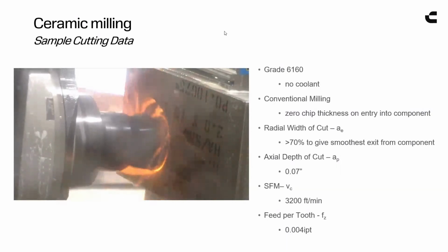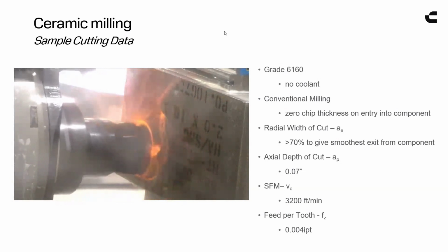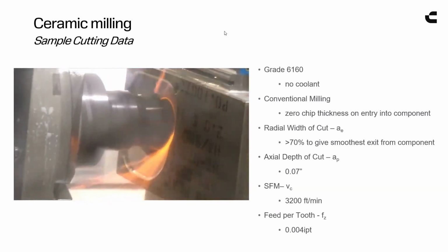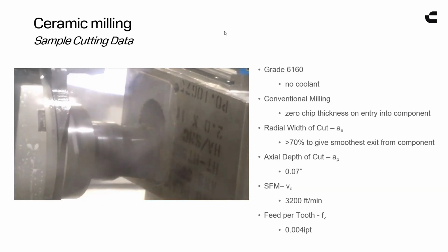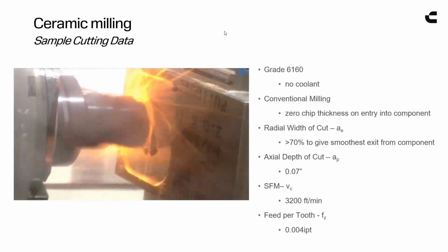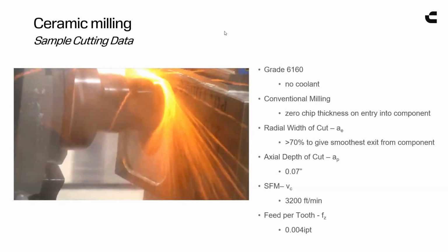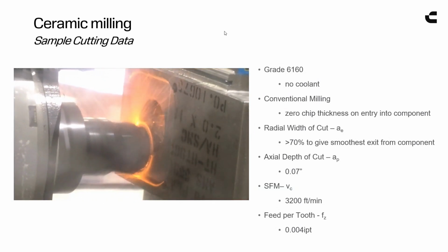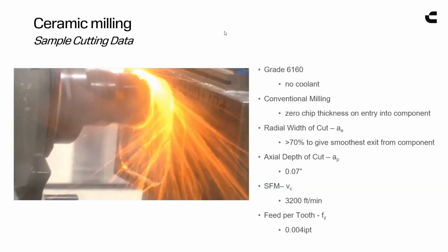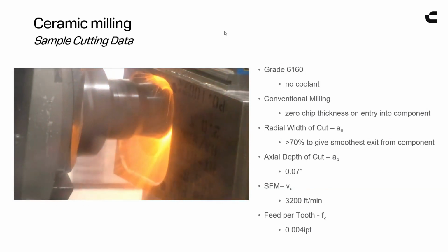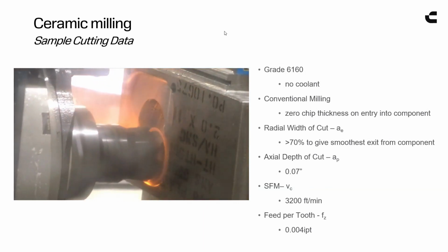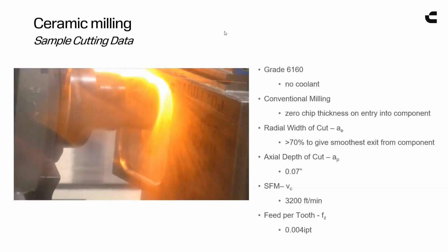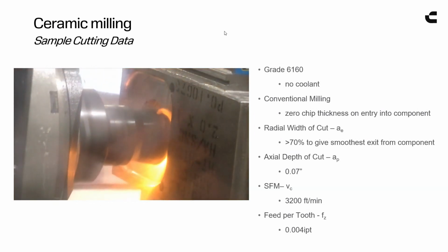This is a block of titanium. Sorry, Inconel. And why it's so important that you do not use it for titanium, because it will cause a fire. It's only strictly for nickel alloys. So I just want to be clear on that. But when you're utilizing it, you don't use coolant. This is exactly how you would cut it in real life, and you're going to see sparks flying. You'll see kind of like this sawdust of sparks, but it's fantastic at removing a lot of material very quickly.